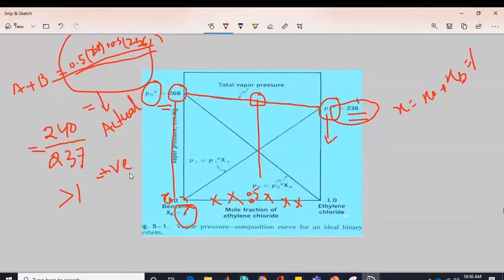Yeah, of course. That's what I'm saying. You cannot rectify, you cannot purify. This is just a basic separation mechanism for different ranges of components. In case you have just two components, like I have given you the example from C5 to C10. In case you have only C5 and C10, maybe you can get higher purities. But still there are chances that those vapors can carry C10 with them. So still you cannot get 100% pure component at the top, or at the bottom.